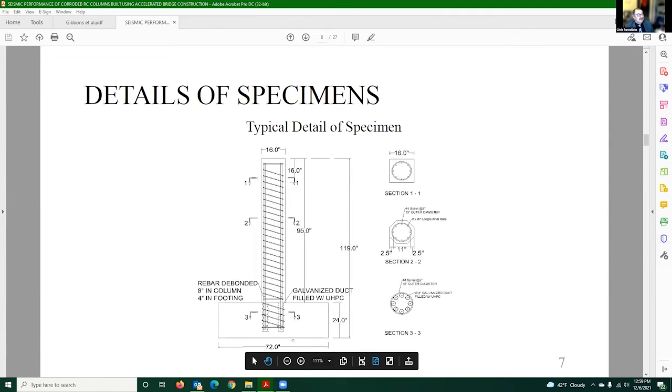the grout that we will use is a grout we actually developed here, which is very high strength concrete. We can develop about 11,000 PSI, which is a very good strength. Our concrete is typically 5,000 to 6,000 PSI. So these grouted ducts work very well. We actually use them in a current project for another project, and they are doing very well.